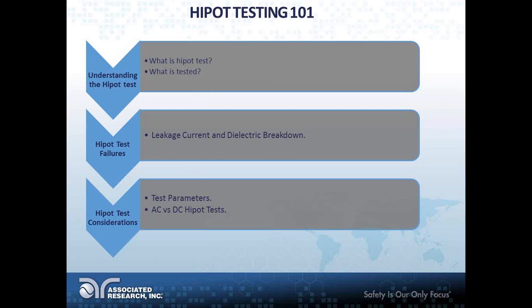So having said that, let's real quick go over why we really need to perform an electrical safety test. As we all know, safety agencies have implemented and enforced electrical safety testing for one big reason: to protect consumers from potentially fatal electric shock. Many of these injuries and electrocutions are caused by either electrical products with faulty insulation or a product with a defeated safety grounding system.